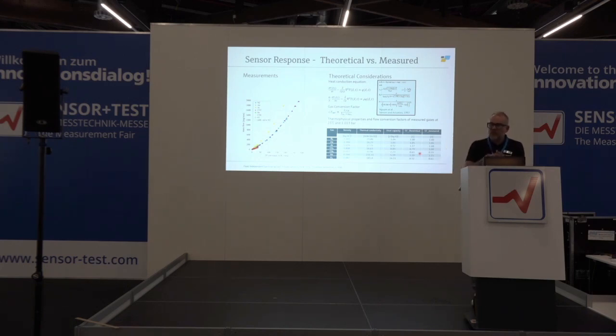So you have to calibrate it once for your type of manifold and sensor arrangement, but then you can store it in your sensor brain and then measure density, choose which gas it is, and then correct for thermal conductivity. You know the 0 point effect, and you know the correction factor, and this can be done automatically.